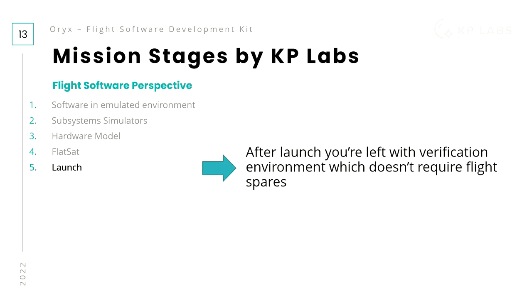So if you want to, for example, update your software, or send some patch, then you can check if on ground it works correctly. You can integrate this and run it on your ground setup with the hardware model only and simulated devices. And if it's okay, you can be quite confident that it will work on the actual hardware in space as well.